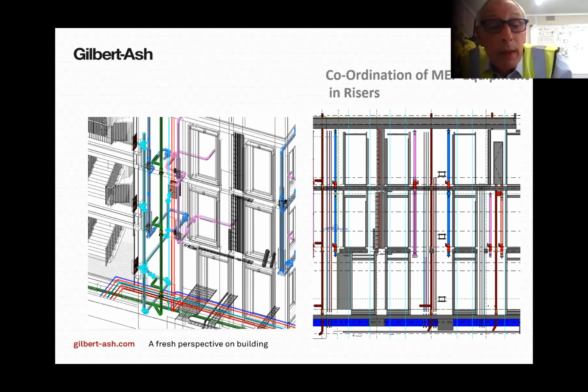So as I say, by building up these detailed models, we can find out where things clash. We work closely with the team to work out where our openings are required, what effects they have, and make sure they're not on top of a column where you would have rebar coming out of the column and tying in the rest of the concrete. And you can actually see the little pink on the left, there's the ventilation, and we've got attenuation contained within the ventilation ductwork, which obviously stops the transfer of noise between the pods. And that's where I finish off.